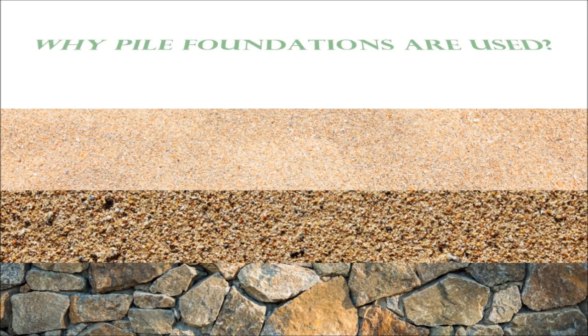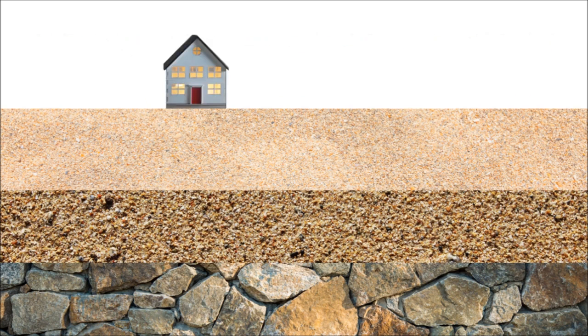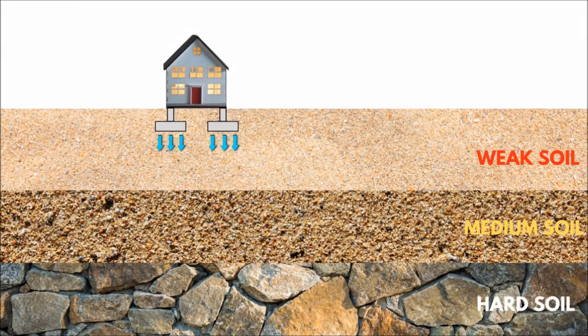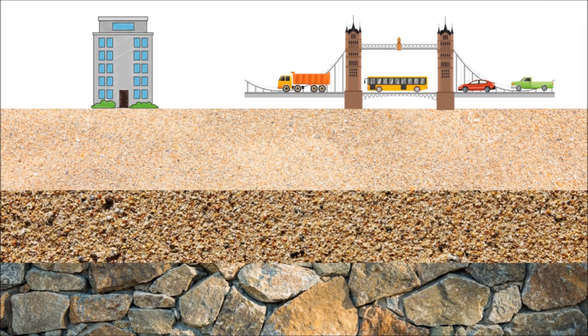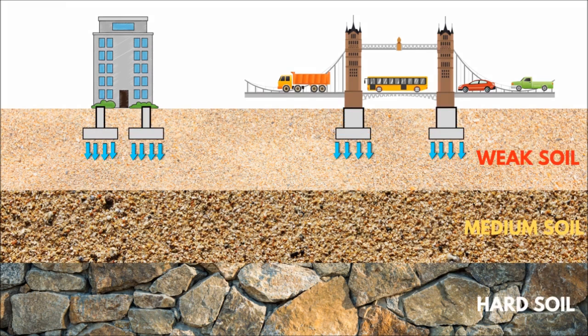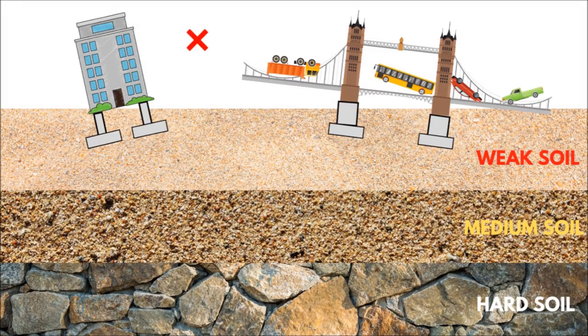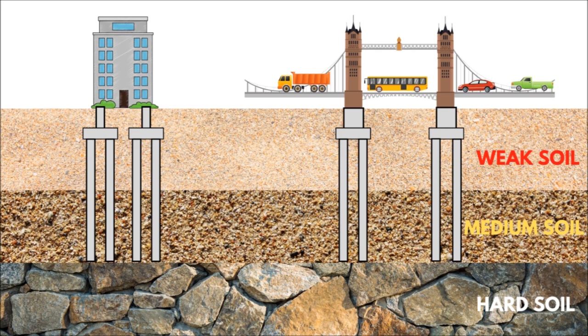Now the question is, why are pile foundations used? When the structural load is less or moderate, it's economical to use shallow foundation, where the underlying weak soil is able to bear the loads. But where the structures constructed are large and heavy, the underlying weak layer of soil will not be able to bear these heavy loads, causing settlement and damage to the structures. Pile foundation is the solution here. It transfers the heavy loads from the underlying weak soil to the lower level of hard and strong subsoil.